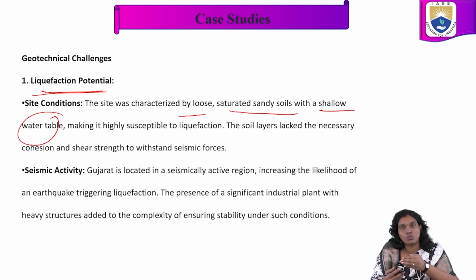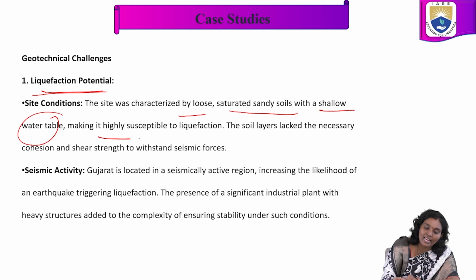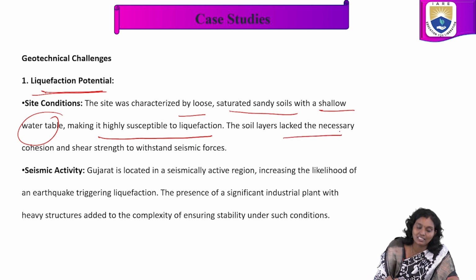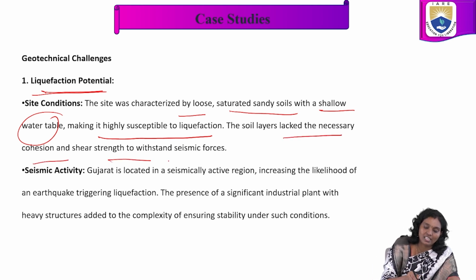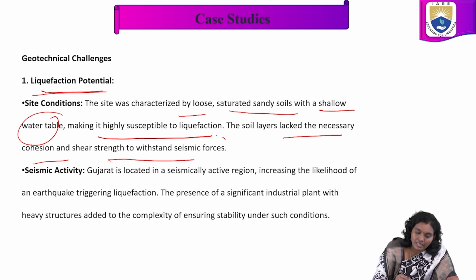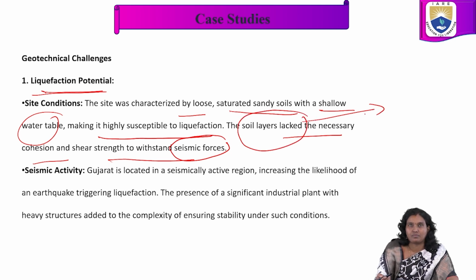Here the site had loose, saturated sandy soils with a shallow water table, making it highly susceptible to liquefaction. The soil layers lacked the necessary cohesion and shear strength to withstand the seismic forces.